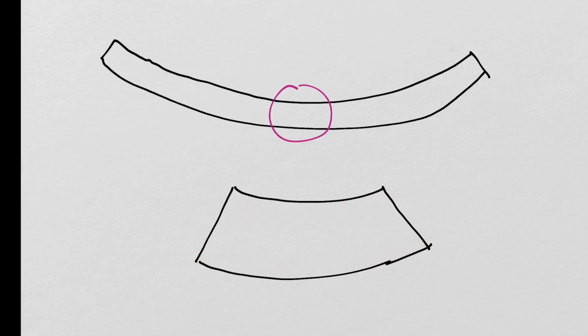Each of these cross sections is considered perpendicular to a certain line, though, and there is a line that is neither stretched nor compressed. It is just as long as it was before the bending. And the reason this is possible is because these endpoints are actually allowed to move. This here is supposed to be these cross sections.